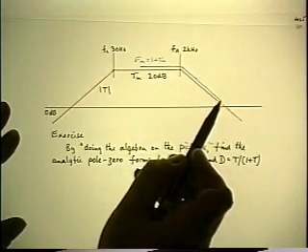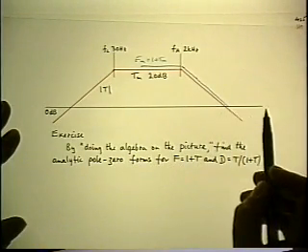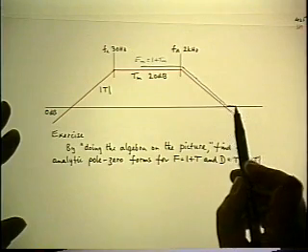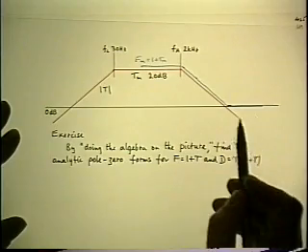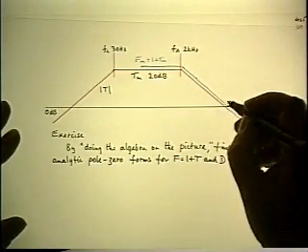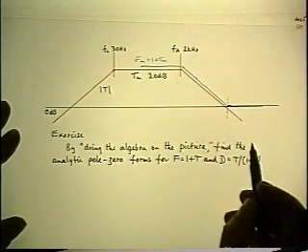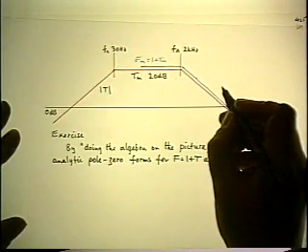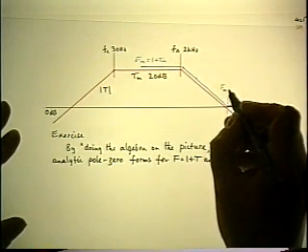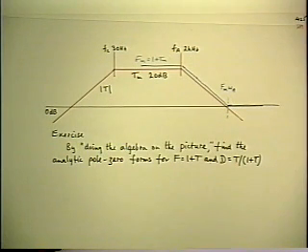And we've already done this part before, and we'll extrapolate that slope until you hit the final asymptote, which has to be 0 dB, because when T drops below 0, 1 plus T will simply become 1, and we've already done this part before and identified this corner frequency by gain bandwidth trade-off as Fm times the omega A. So that's exactly the same as we did in the previous example.